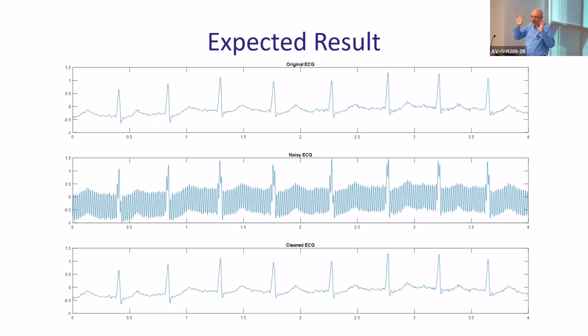Because you don't know what the signal subspace looks like. It's complicated, depends on the signal. But you know how the noise would look. So you want to project to that subspace of noise, sines and cosines type of thing. And then you subtract that subspace of noise from your original signal. You get the signal. Practically, you're thinking about the signal as signal plus noise. You're computing the noise, which is a 60 Hertz sine, and then you're just subtracting that.